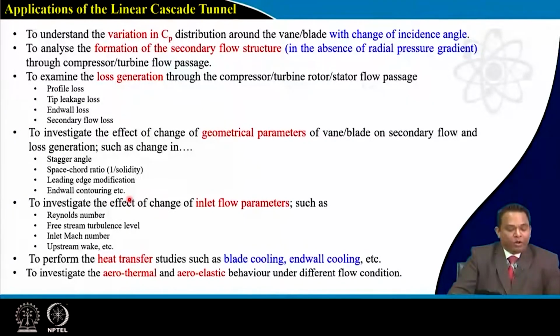We can also investigate the effect of inflow parameters like change of Reynolds number, maybe free stream turbulence, inlet Mach number, upstream wake effect. All those things affect the performance of an axial flow compressor. So before making a design, people do all this kind of study using the linear cascade tunnel.